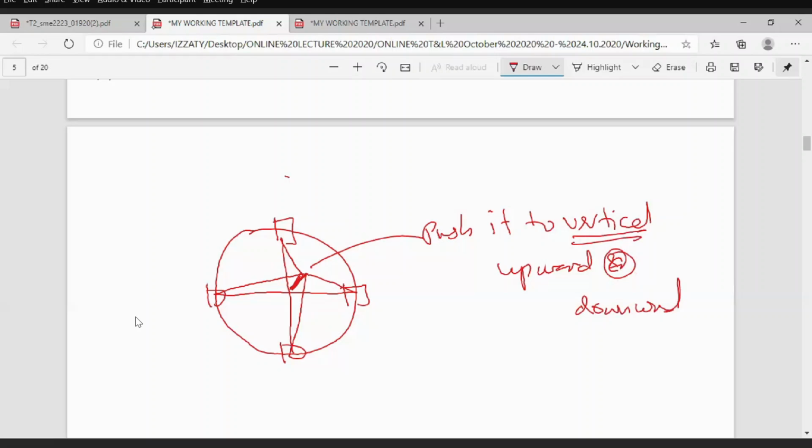Am I answering your question? Can we use horizontal, if the question gives the reference of 0 degree at the horizontal? Yes, you can. Let's say this one is the 0 degree side. If you use this one, it's still okay. But you have to ensure that your crank's opposite direction will be that one. It's very difficult for you to ensure that. The easy way is to put it vertically, even though it is not 0 here. Supposing this one is 90 degrees or 180 or 270, it doesn't matter, but vertical. Typically, this is not decided by the equation. You decide, except for the inline engine. For the radial engine, you decide where the 0 falls. Okay, Doctor, understood. Thank you.